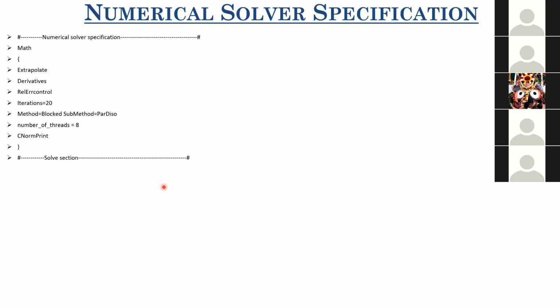Now the solve section, how exactly do we mention what exactly are the voltages or currents that we want our device to go. So here we go ahead with solve, and this init one is the plot file. Then first, as I told, we go for initial solution. For finding the initial solution, we only solve the Poisson equation.